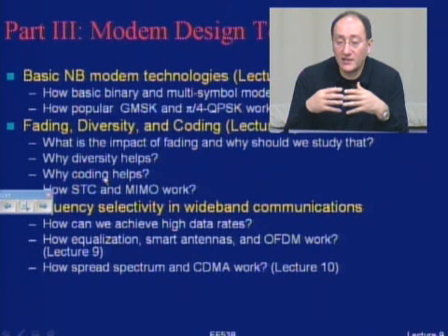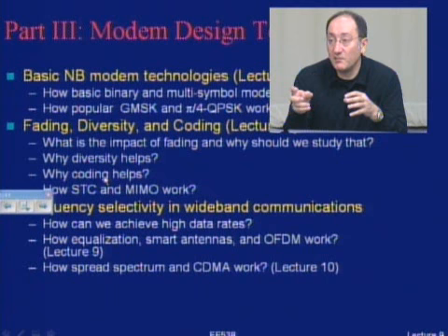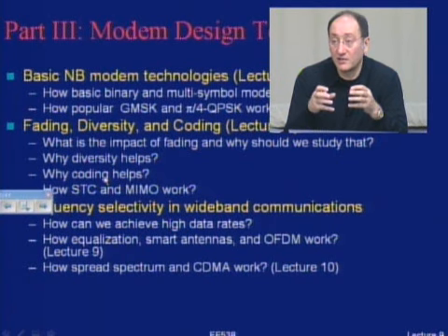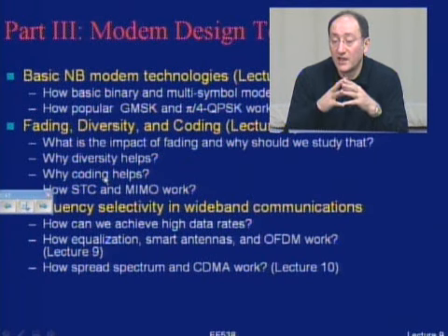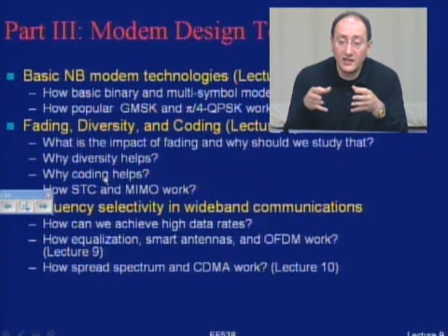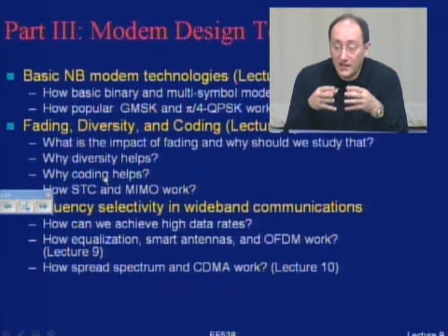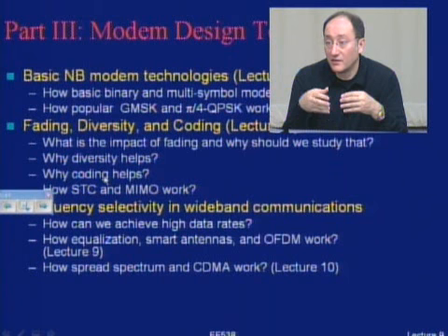But in action, the difference is that if I send a pulse in narrowband, I receive the same pulse shape. In wideband, the shape of the pulse gets distorted due to multipath. That's the basic difference. And then the question is how you can remedy that situation. And then I review the techniques which are applied to remedy this situation.